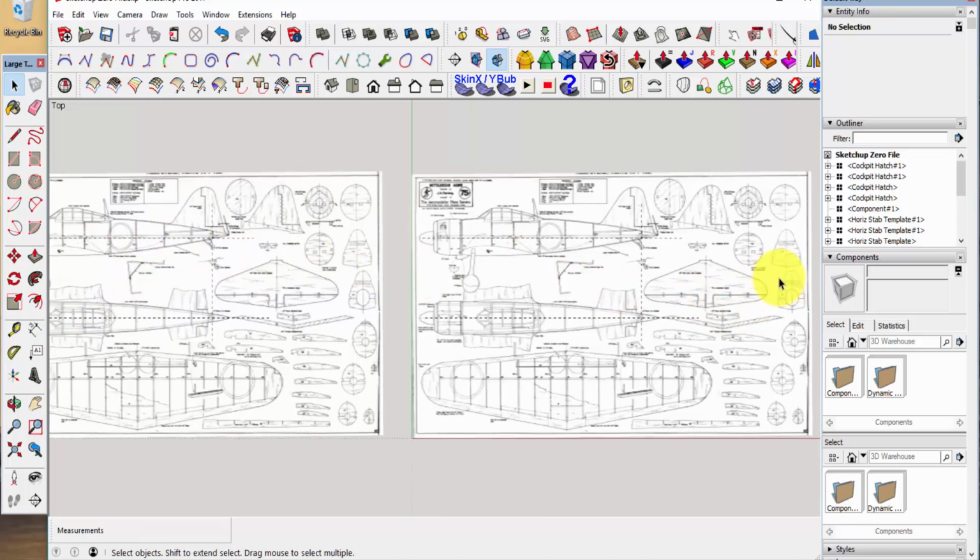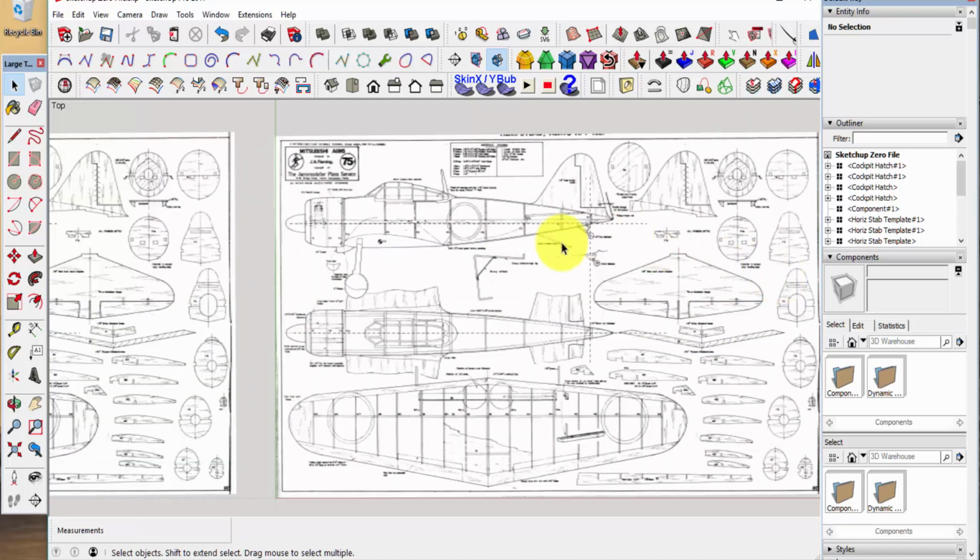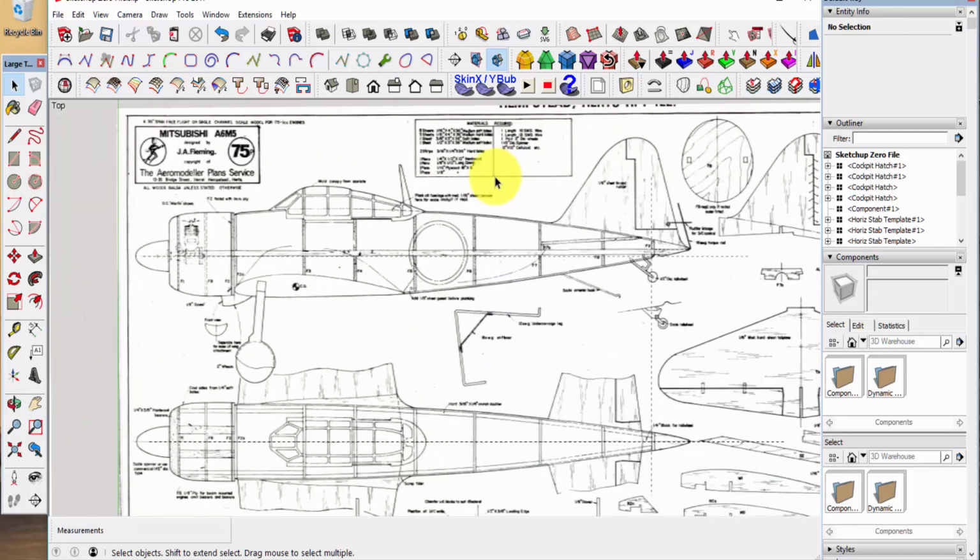Now recall that we said that the EPS foam thickness was 48 millimeters. So what we're going to do right now is come in and make 48 millimeter segments or slices through the fuselage side view. I just selected T for the tape tool, and of course, as always, the tools are also over here on the toolbar. I use shortcuts a lot just for speed. So T for tape, and come here on our very tail end Charlie former, which is F9 in the model.